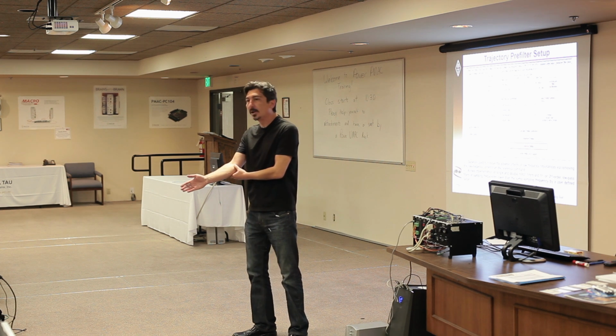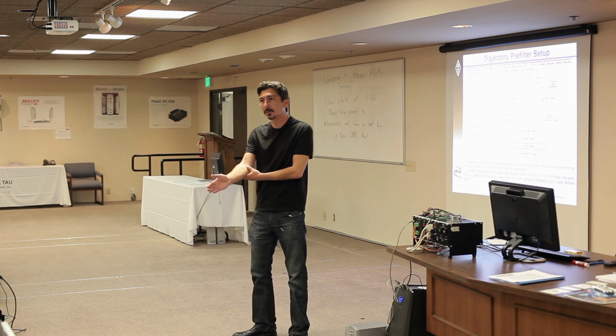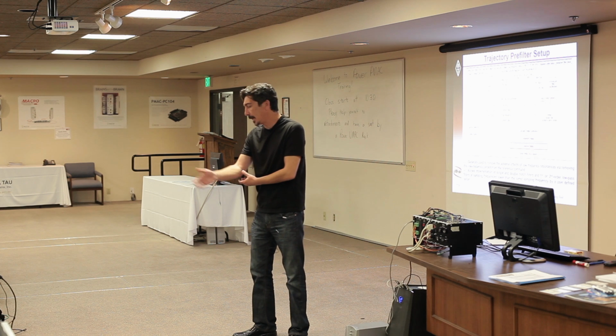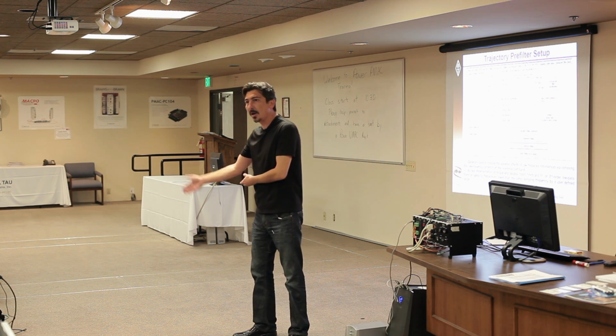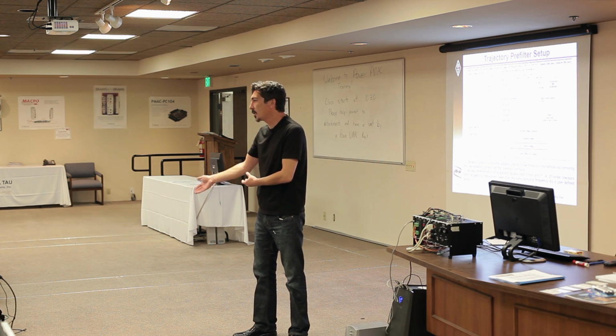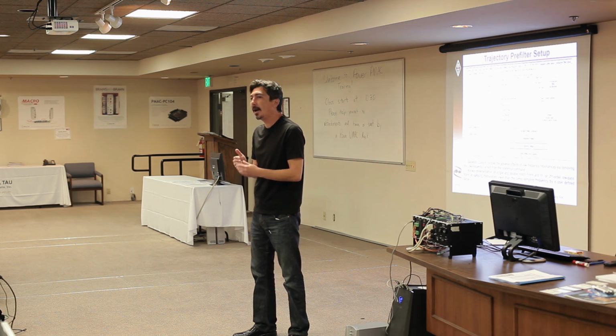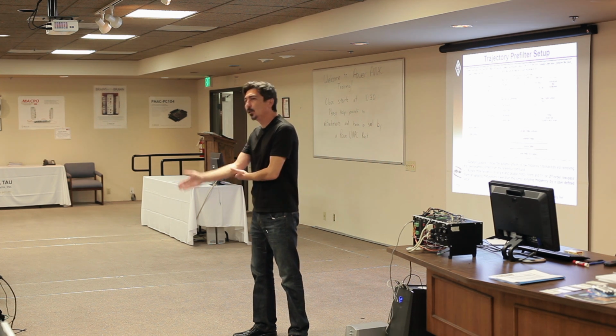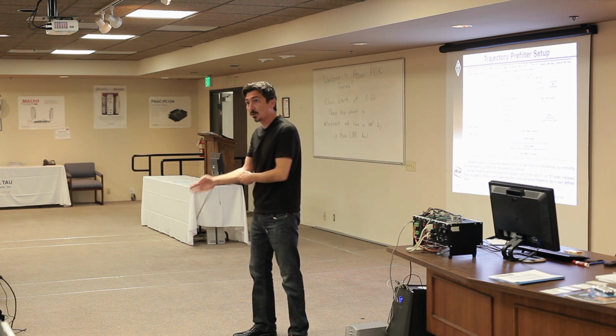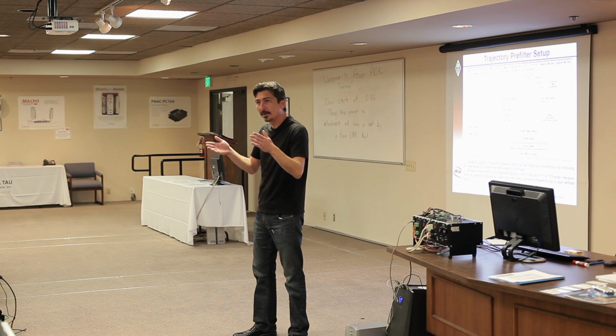Either you can move it really, really slowly, okay? But for a pick and place robot, this is going to take too much time. The throughput of your machine is going to be really low. But there's another idea. Why not try not to excite exactly that frequency? If you do that, you can still move fast, so you can have a really high bandwidth again.